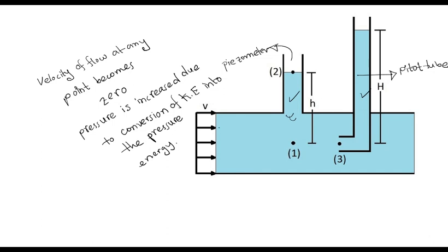So when a solid body is kept centrally and stationary in a pipeline with flowing fluid, the velocity of the fluid starts reducing. At the same time, pressure increases due to the conversion of kinetic energy into pressure energy. Directly in front of the solid body, the velocity becomes zero. This point is known as the stagnation point. B3 is the stagnation point.